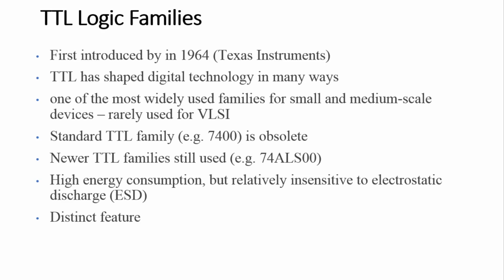Starting with the first one, the TTL logic family, first introduced by Texas Instruments in 1964. TTL shaped digital technology in many ways. It is one of the most widely used families for small and medium scale devices, rarely used for VLSI. Standard TTL families, for example 7400, are obsolete, while newer TTL families are still used. High energy consumption but relatively insensitive to electrostatic discharge,